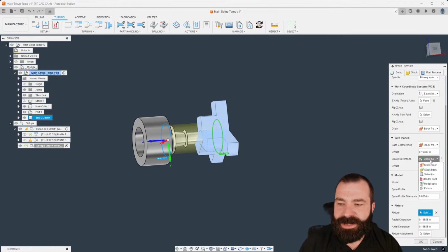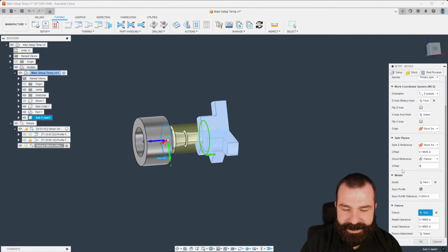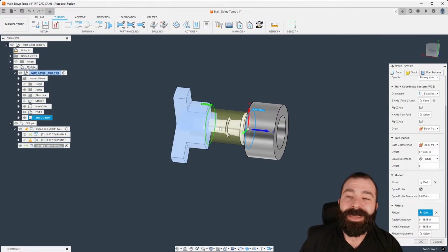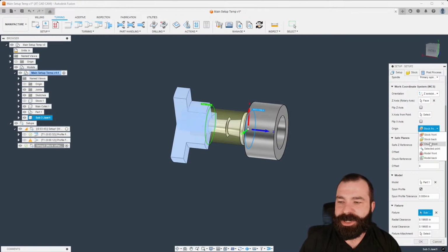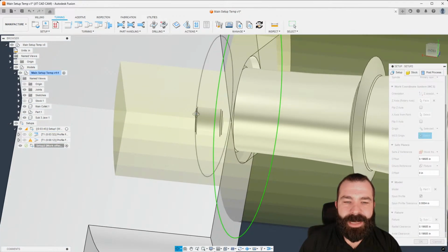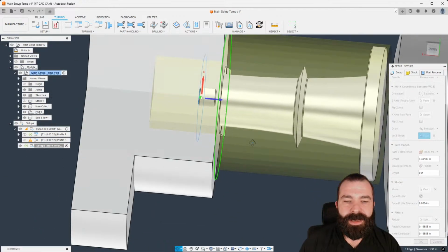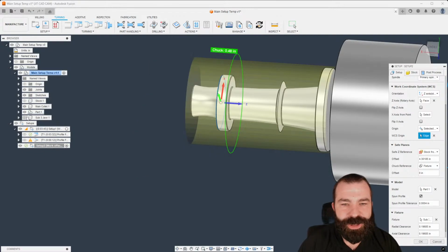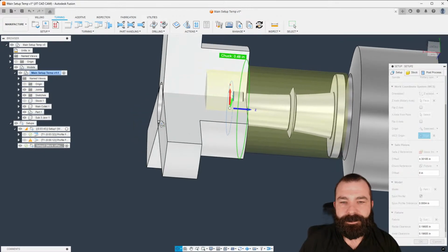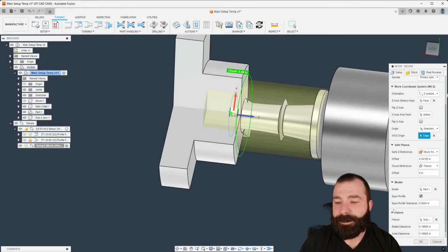My fixture this time is going to be based on that sub 3 jaw scenario. And of course, as you guys know, we could go ahead and set things like based on our fixture, we want to be at 0, however you plan to set up and control everything, right? Given we are making soft jaws, another thing we may want to do is instead of using an origin based on a stock location, maybe we're using a selected point. And that selected point might be a hard shoulder here. As you guys will see here in a minute, if I get my 3 jaw out of the way, I'm using that square edge on that actual part to set my work offset for my sub spindle.